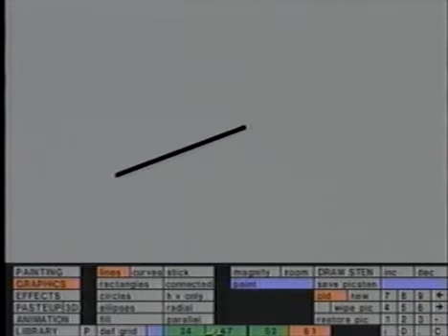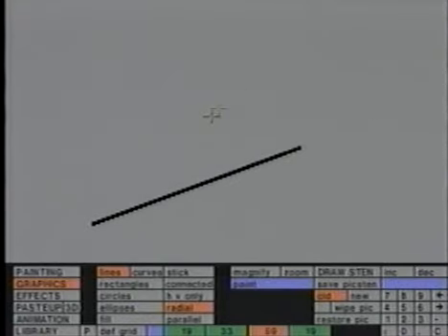Radial lines are defined slightly differently. Changing the X value repositions the whole line, as does the Y. The third box controls the line length, and the right one, the angle.